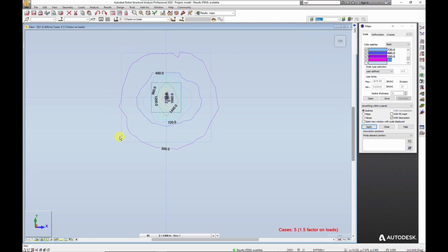So again, using this type of method is very much a matter of judgment. Are we concerned with this small area outside? The bulk of this contour is within the control perimeter, suggesting that we've got adequate resistance. We've got this bit outside of the perimeter as well, so that would indicate this area here and this area here might be overstressed. But again, this is an elastic analysis, whereas we know that punching is a more plastic effect. These are the things you need to think about and consider in doing design, certainly in terms of shear design.